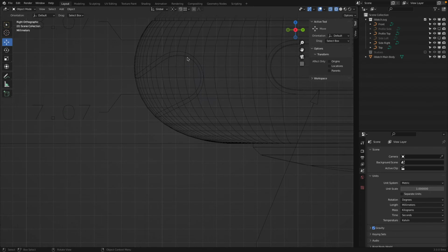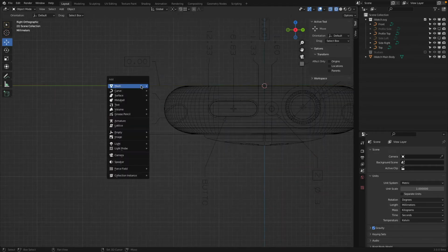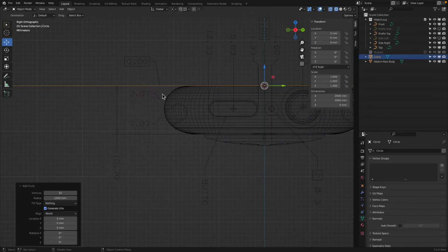Go to a side view, wireframe, turn this on. And we want to model this. This looks like a circle, and then there we have a line and there a line coming out. Okay. So Shift A, circle, how many points? 32. Let's go with 64, so it's nice and smooth. 4 millimeters. Along the y-axis, 90. Whoa, way too big. 2 millimeters.